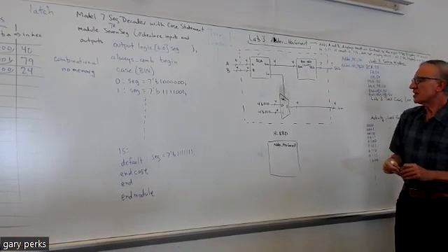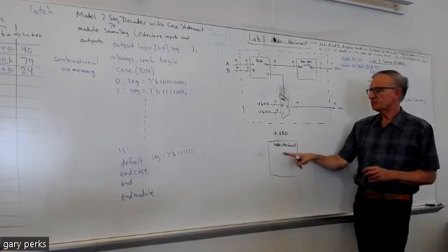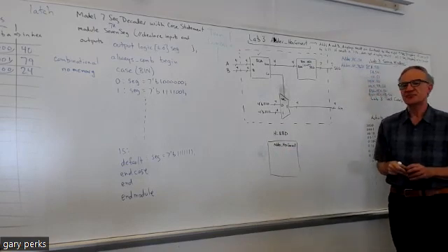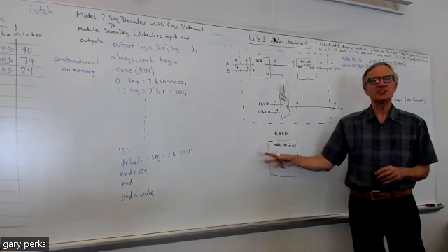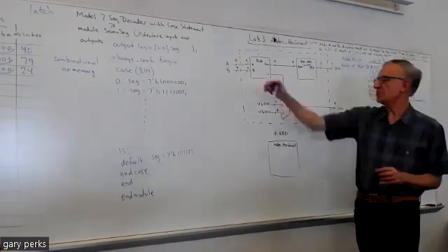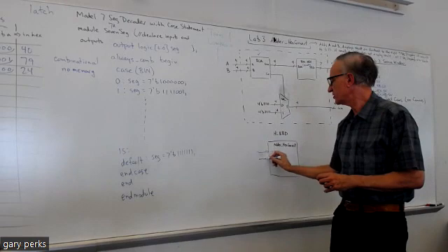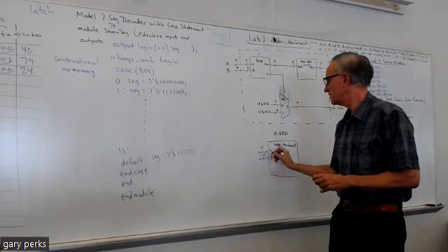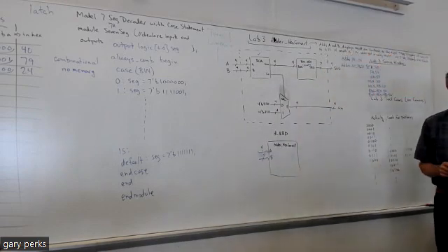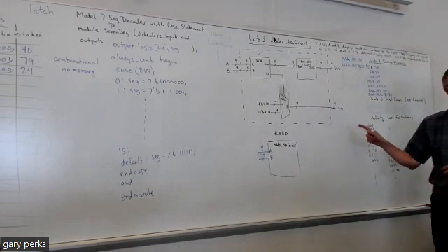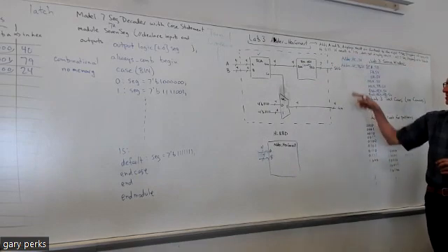Okay, but let's look at this diagram and let's put in the inputs and the outputs for our high-level black box diagram for this adder hex converter. So how many main inputs do I have? How many? 2. A and B, right? The 2 4-bit numbers that are going to get added. Now, how many main outputs do I have? How many? 2, right? What 2 are the main outputs? Yeah, seg and AN.